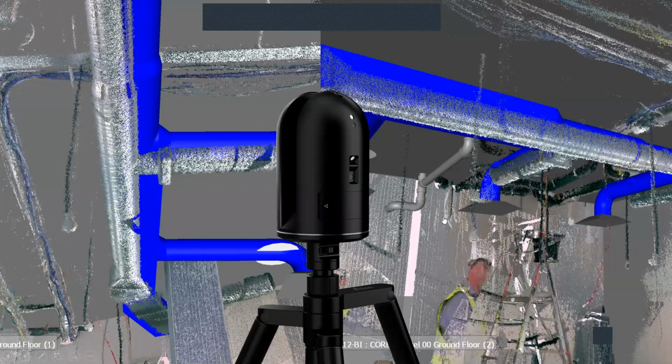For a small contractor who just does jobs of AEC installation or just ducting installation, or interior refurbishings, or the installation of various other components, you can use a small scanner like the BLK360, where you can compare your reality along with the installed components and the Revit model, and you can see what components are missing and what components need to be installed. This is all about what we can do.